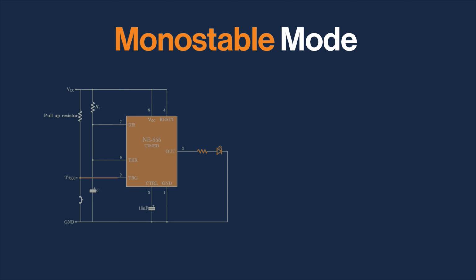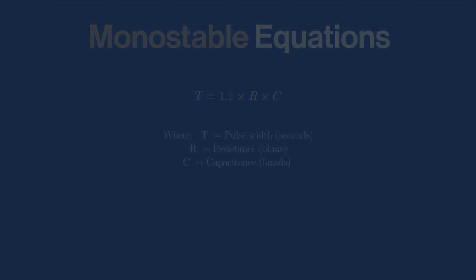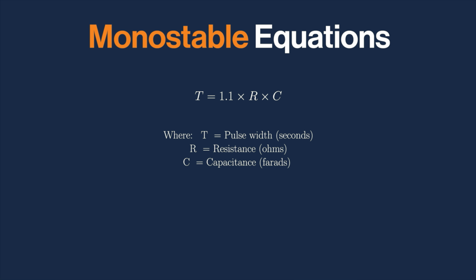And this is great for blinking LEDs, making beeps, or generating clock signals, which we'll talk about much later on. Secondly, there's monostable mode, also known as one-shot timer mode. And here, when triggered, it produces a single pulse. After a delay, it just resets itself. And this is usually used for things like timers, delays, or PWM control. Again, timing's all in the math. Resistors and capacitors decide how long the pulse lasts. For example, think of pressing a button which activates a buzzer for exactly 1 second.